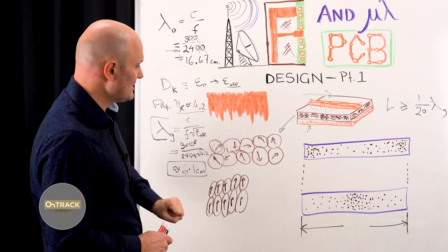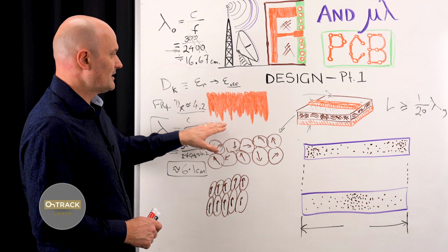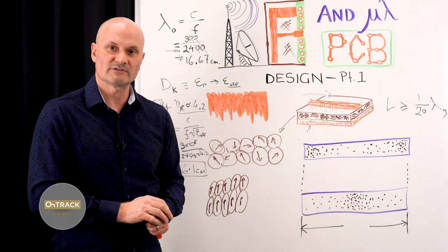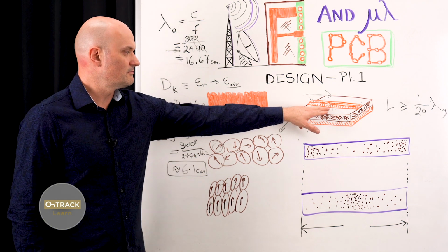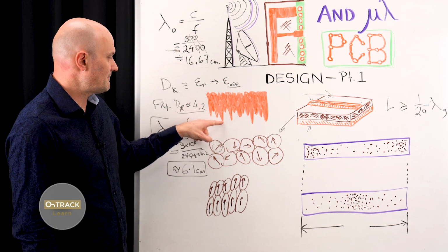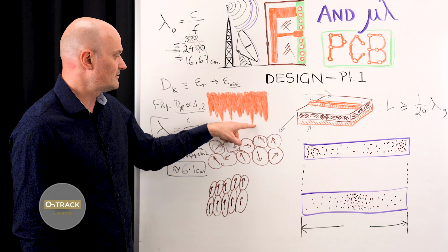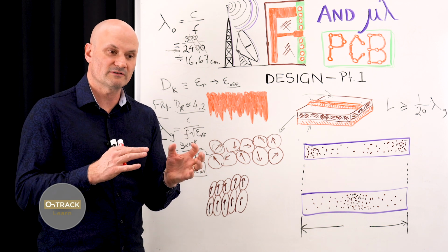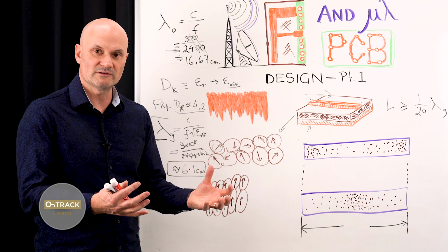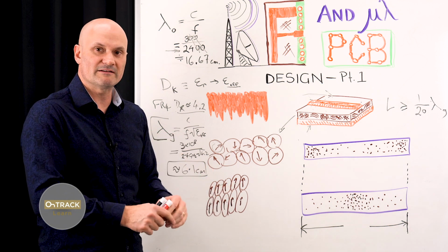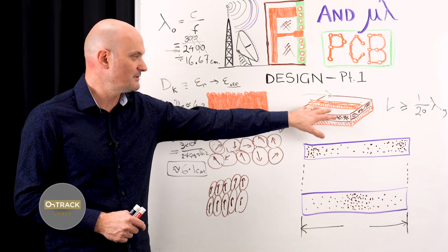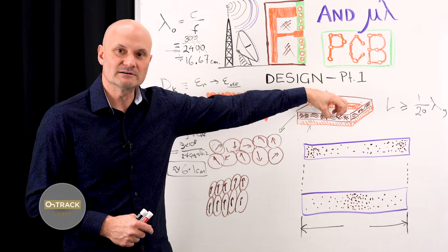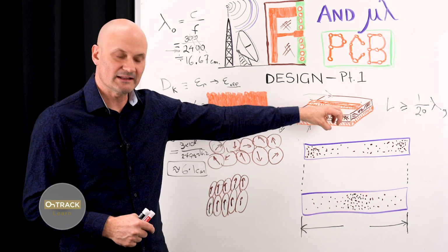Let's talk about conductors a tiny bit. Here I have a cross-sectional view I've drawn. If you get a section of a small PCB trace and you look at it under a microscope and it's polished, you'll see the surface of typical PCB copper is very rough. It's actually intentionally made this way. They take the copper and it comes off a drum, and one side of it's smooth and the other side is rough. It's called electrodeposited copper because of the plating bath that's used to get copper out of solution onto a drum. And they make the foil out of that, and they want it rough on at least one side because that helps it adhere. This tooth, this is called the tooth, and that helps it grab into the insulation material during the lamination cycles.